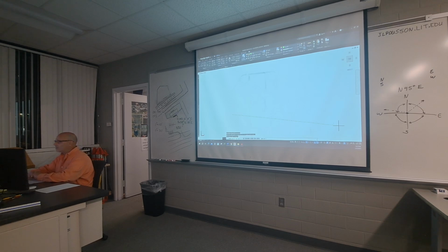At the distance, is less than, the angle, which is south 8 degrees. So you can see that I typed in S8D, because once again, there is no degree key on here. The D is telling AutoCAD this is degrees. So S8D, south 8 degrees, 16 minutes, which is your foot mark, 18 seconds east.